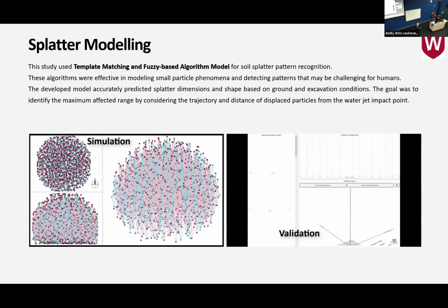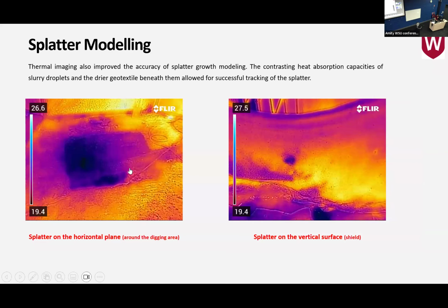That's very similar. Look, during COVID, everyone was trying to model a sneeze, how big the splatter would be, how big the impacted area would be. That's very similar to that concept, that when you hit the ground, how big the splatter would be. Out of that simulation, we developed a guideline, a rule of thumb: 5 meters was safe, with the typical pressure, with the typical soil around Sydney. So as long as you have an exclusion zone of 5 meters, you will be safe.